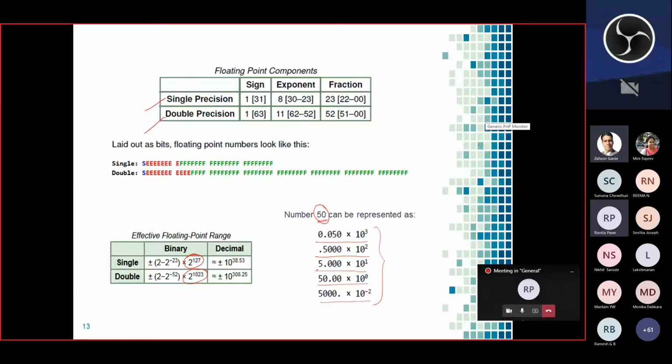Whereas in fixed point, you can do decimal number operations, but the decimal point cannot be moved. Let us say you want to multiply 0.00238 with, say, 0.00567. Whatever answer you get, after the decimal point you can represent only 5 digits, let us say. After those 5 digits, you cannot know what digit you have. Whereas in floating point, you can move the decimal point. Something like 1358 into 10 raised to minus 4 can be held here. You can move the decimal point, so you can make the calculations precisely. This is the major advantage of floating point processors.